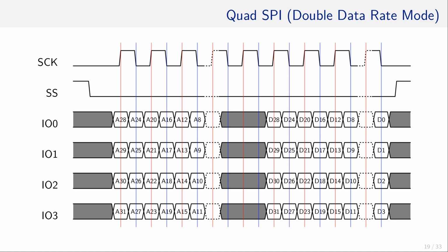Important to note, there is no formal SPI specification precisely defining how the master and the slave arrangements have to look like, or when the data is sampled. There are even more settings which might differ from SPI device to SPI device, and the developer has to consult the datasheet beforehand to figure out if a new SPI device is compatible with eventually already existing SPI devices in the topology. So it is a good idea to consult the datasheet even before purchasing a SPI device. It might not be compatible.